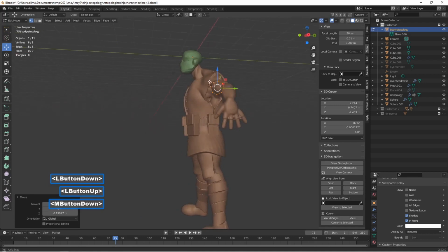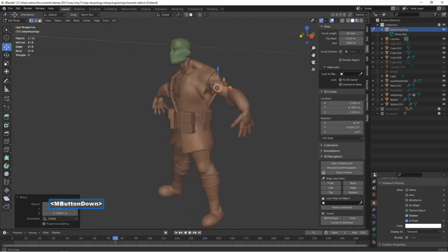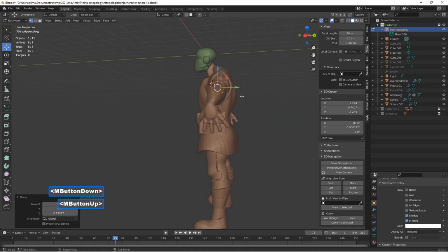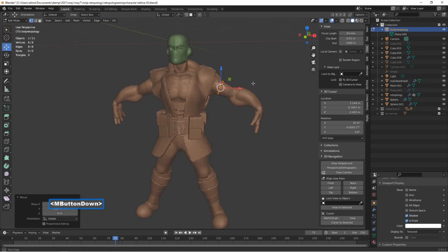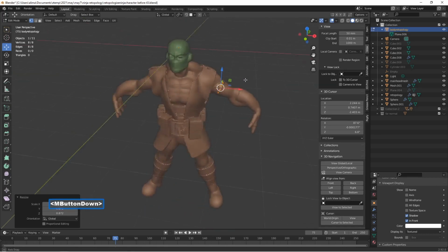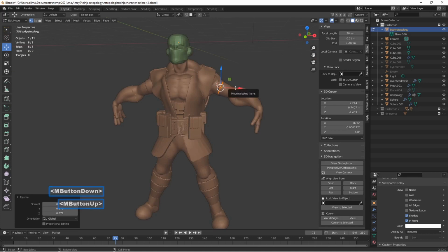To make sure this is placed inside the arm, you're going to have to rotate your view. You'll find that if you try to do just a front view, you'll have a hard time seeing where objects are at in 3D. When you're doing this, you want snapping to be off. You don't want this to be too high up.